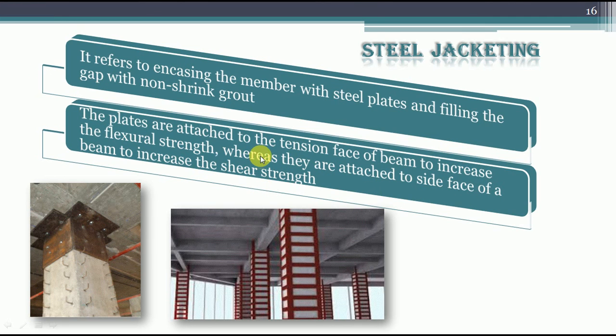Here I included an example of the beam. The plates are attached to the tension face of the beam to increase the flexural strength, whereas they are attached to the side face of the beam to increase the shear strength.